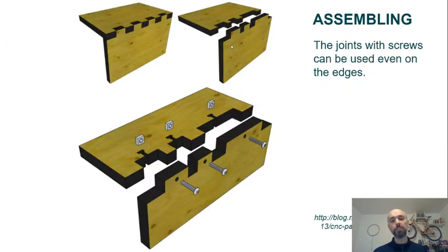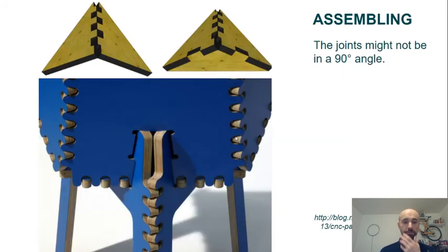Same thing as we said, you glue things or you screw things, the concept is the same. You can be symmetrical or not. Here you see solutions for a pretty thick wood. When it becomes thinner, there's the risk that this hole gets too close to the line. So usually at that point, you design a sort of bump or extra material around the hole just to make it more robust, but it's a tiny detail.